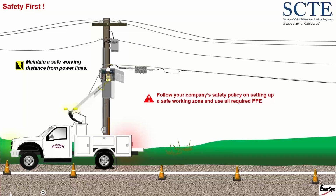Also with safety, we work up close to the power lines. You want to make sure you maintain a safe working distance from the power lines. I don't have the National Electrical Safety Code safe working minimum distances from different voltages on this chart. I used to have it on here. I took it off because really what I want technicians to understand is you don't know what the voltages generally are up on those power lines. So stay as far away from the power lines as you possibly can.